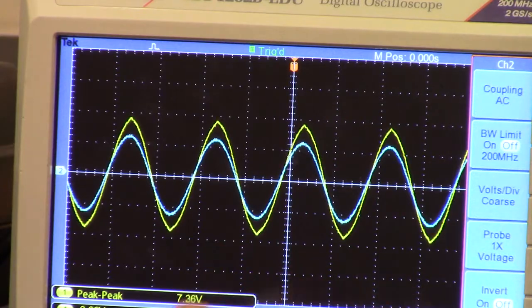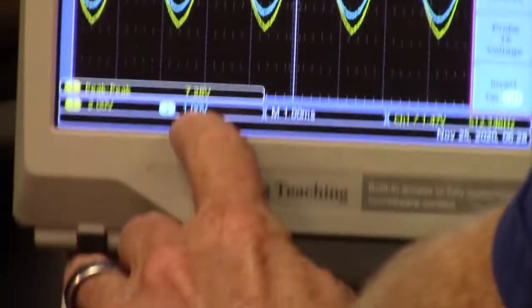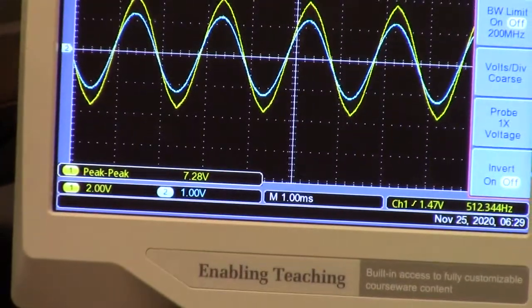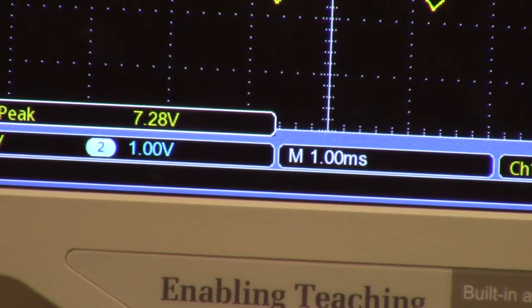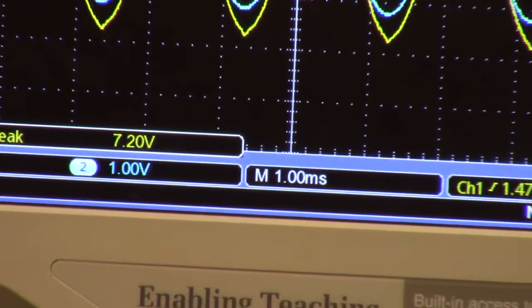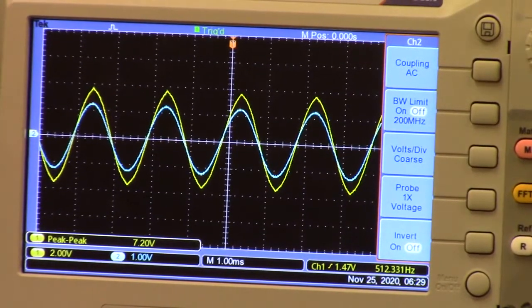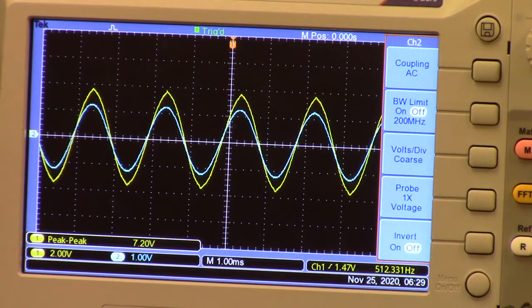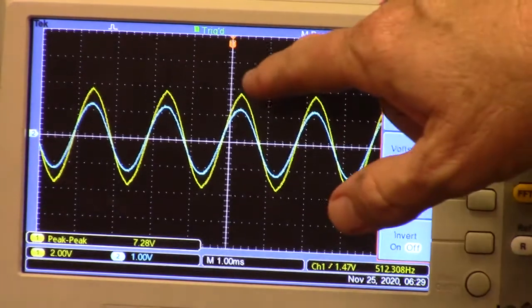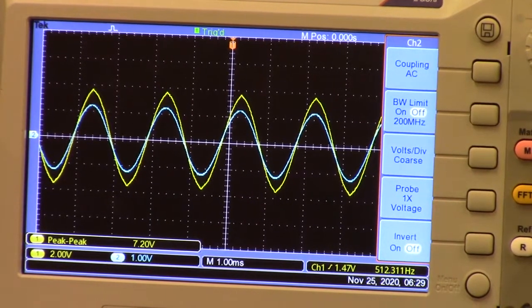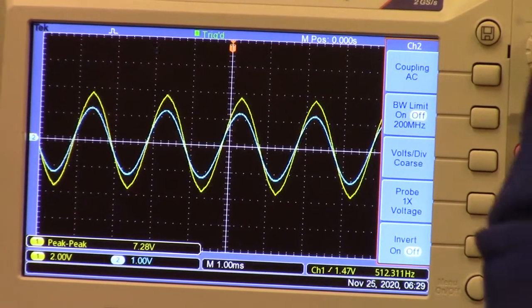Okay, so again, channel 2, it looks like it's saying 1 volt per division. So it looks like channel 2 goes up about 1 division, so that's 1 volt. And remember, divided by 10 ohms, so that would be 0.1 amp. Okay, so it's what I'd be getting right now. Okay, now, before I even begin my measurements, let me show you something kind of cool here. You will see that in this setting right now, the voltage and the current are peaking at about the same time on this display. Maybe not exactly, but pretty close.